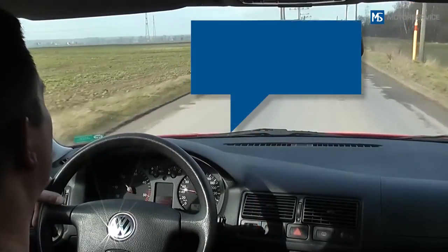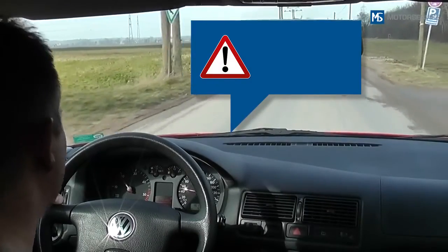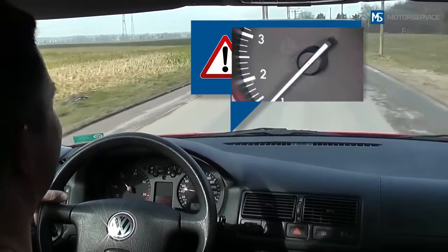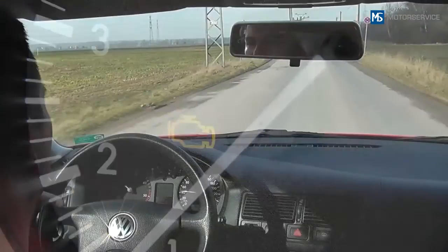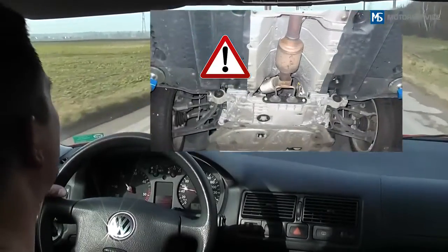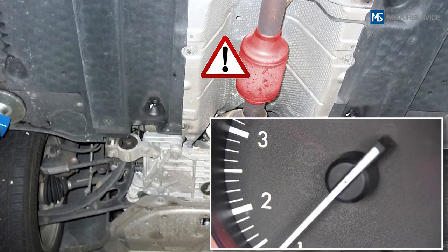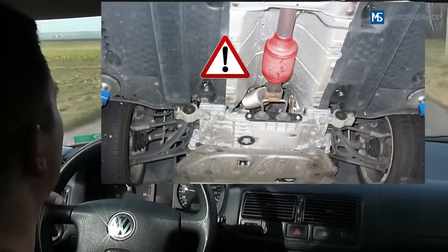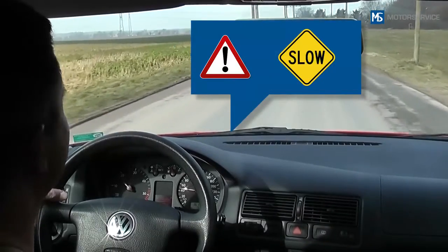If an exhaust gas-related fault occurs, or if a fault is detected during self-testing of the control unit, the OBD fault lamp lights up continuously. If a fault occurs that leads to cylinder shutoff or to damage of the catalytic converter, the OBD lamp flashes. Depending on the severity of the fault, limp home programs may be activated to protect the engine.